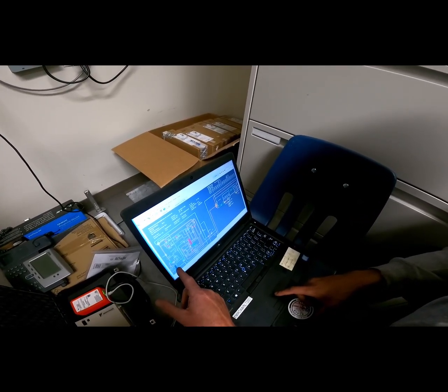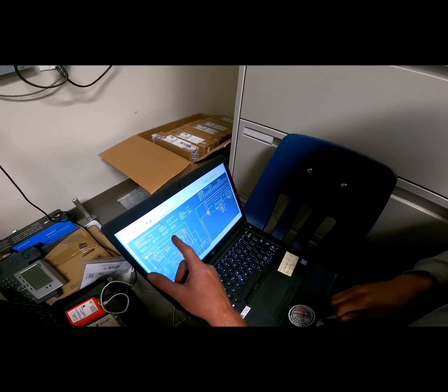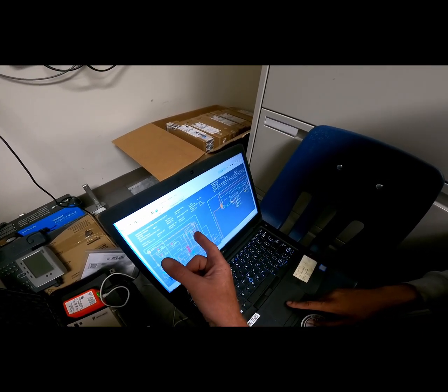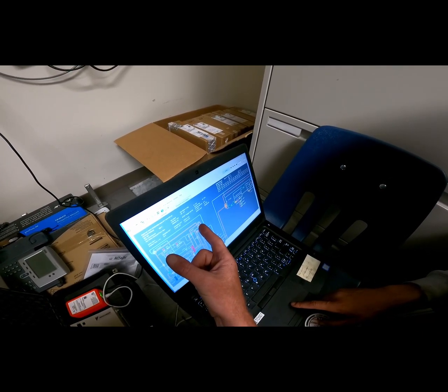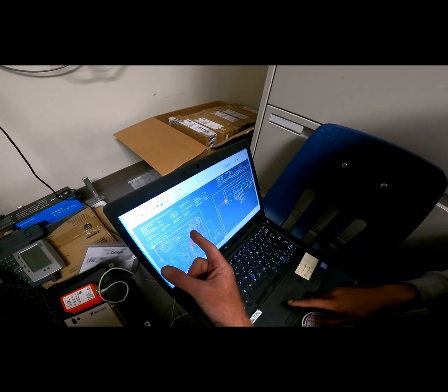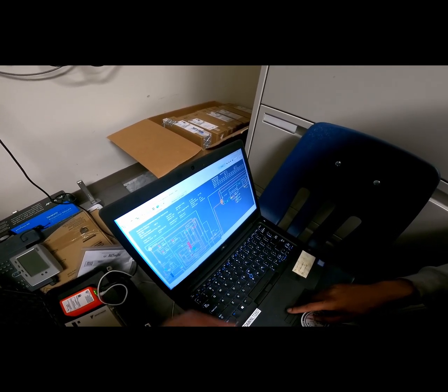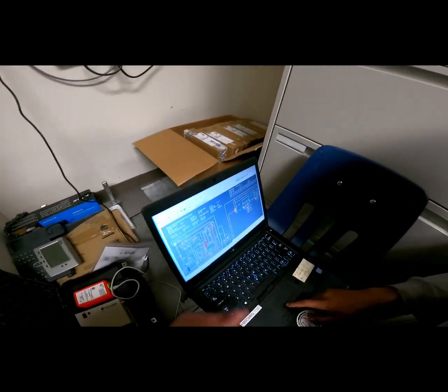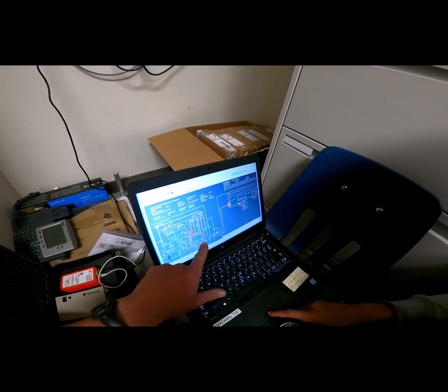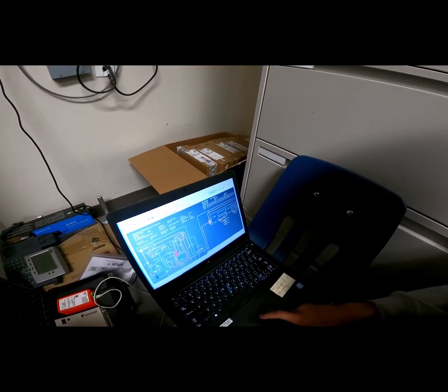So you're sending hot gas out of your compressor. It's going through a reversing valve here, a 4-way valve. It's coming down here. Looks like it's taking a turn here and going through a solenoid valve 7, coming down here, going through some more solenoids, and then going into these heat exchangers at 86 degrees. Then it's coming out. It's going down here. It's coming out of the unit, and then right here it's going into your branch controller.